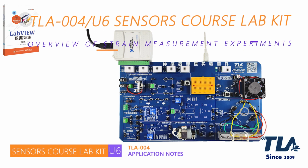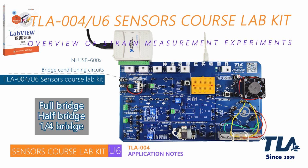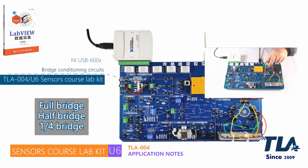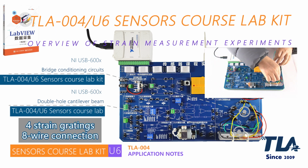Module 12 is a bridge conditioning circuit module, which provides a bridge structure circuit required for strain measurement. Through configuration and setting, the full bridge, half bridge and quarter bridge structure can be flexibly realized. More specifically, the TLA-004 sensor experiment kit provides a double-hole cantilever structure on board, located in module 11.